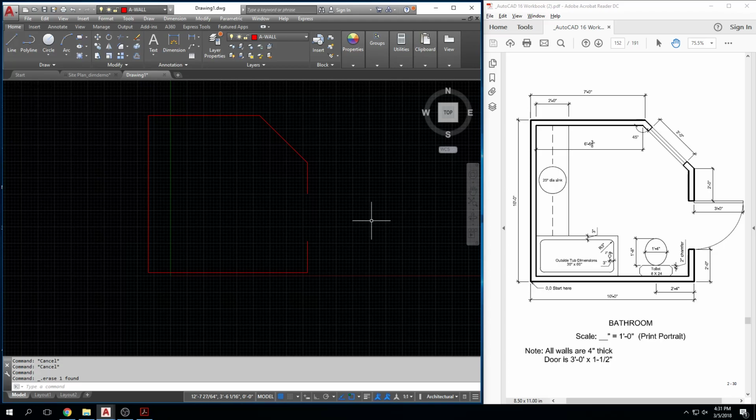So did you turn off your auto here? And then you connected the 2 foot line? F8. Turn it off and connect it. So if you have a little bit of extra geometry, you draw a few extra lines, that's okay because that's how AutoCAD works. Okay?